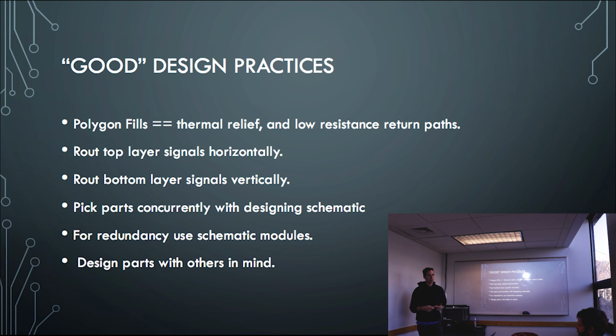It simulates ground bounce, signal integrity across the line, characteristic impedance and stuff like that by changing the layout, and then also you can change the characteristics of the PCB material, and also look at inductance and stuff like that.